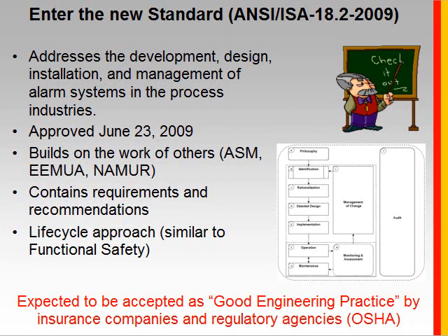Because of all those reasons, the process safety accidents that we talked about and those common alarm management issues, in the U.S., the ISA 18 committee went to work in 2003 to create a new standard on alarm management, which was completed, released and approved in June of 2009. And it addresses everything you need to do in terms of design, operation, maintenance, management of alarm systems in the process industries.